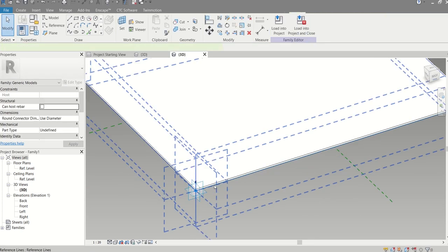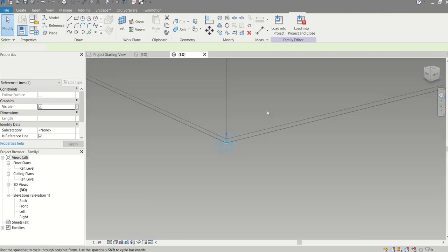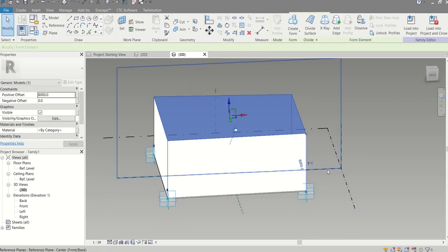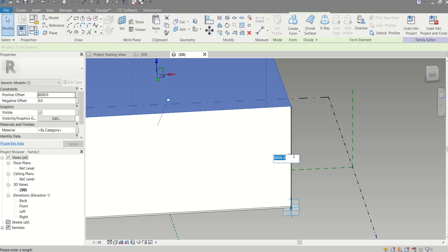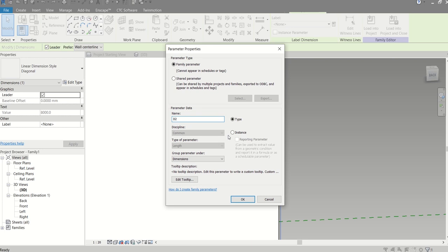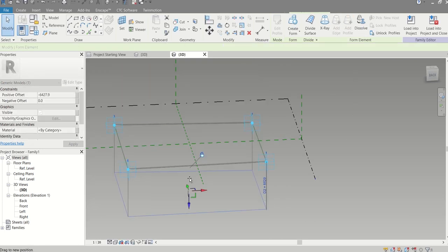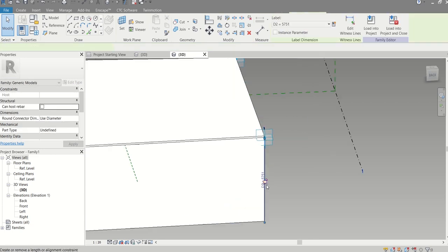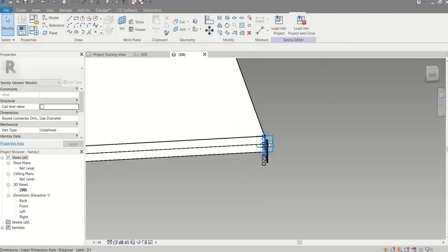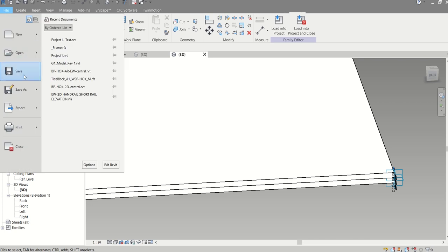And I'll do the same process again. Since I want to get it nicely offset bottom and up, I'll generate a solid form again. And that's done, and create another one. Select the theme. You'll have to select the theme again and create another one, which will be D2. Family D2. Click OK. Push it all the way back there. D2 goes to 100. There you go. So now we have 100, 100 equal offset. Now go and save this.